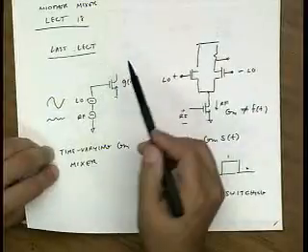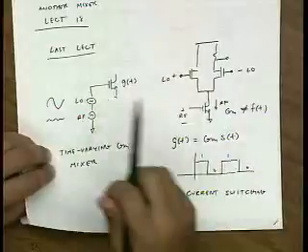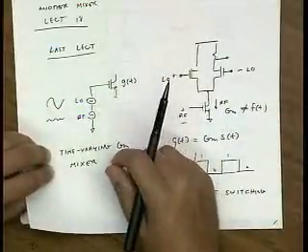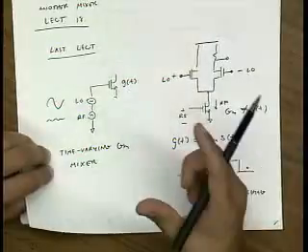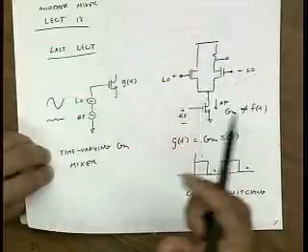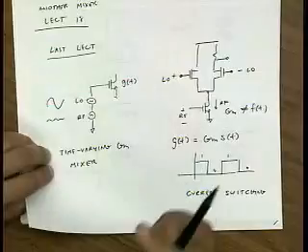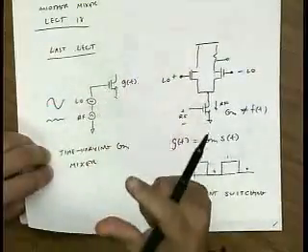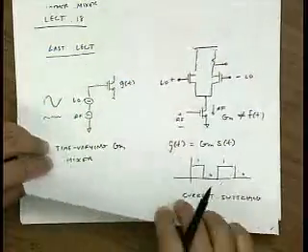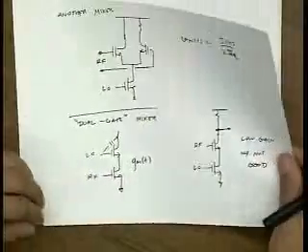Okay? Now, LO leakage, why is that bad? Well, usually the next stage after the mixer could be another amplifier, or it could be an A to D converter. And if you have a large LO swing going into that A to D converter, you could completely clip the next stage. It could overwhelm the signal because its strength could be a lot larger than the RF converted signal. So it's much better if we could get rid of that LO. Similar argument applies for RF.